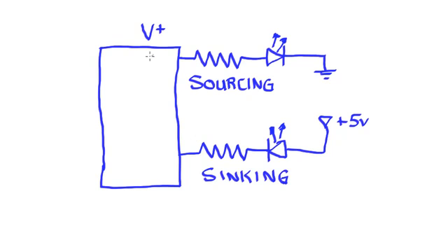In this top example, I said that in order for the LED to light, the port would have to go high because whenever an output goes high, the connection to our V positive is being made. The LED would go off whenever this port goes low. The opposite is true with syncing, that the output will only go on when the port is low because that's when the connection to ground is being made. And when we have that connection to ground, we have a complete circuit from the positive 5 volts to ground. When it goes high, that complete circuit no longer exists.